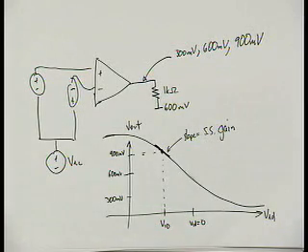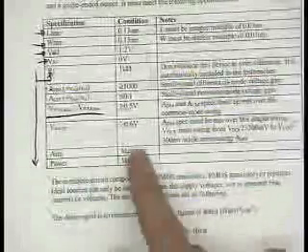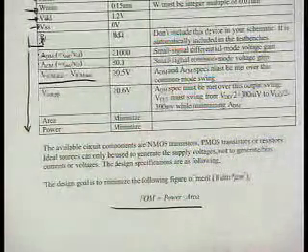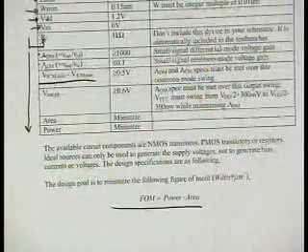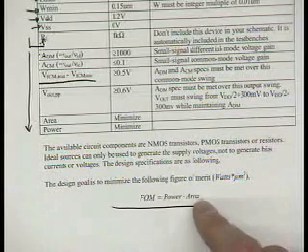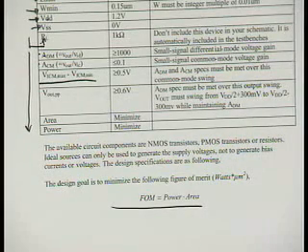All right. So I'm going to move along now. The other specs on this sheet are area and power. Those specs you want to minimize because, as it shows down here, the overall goal of this design is to meet all those specifications while minimizing the product of power and area. Okay? And by area, we mean gate area. So it's the WL product. It's the sum of all the W times L's of all your devices.